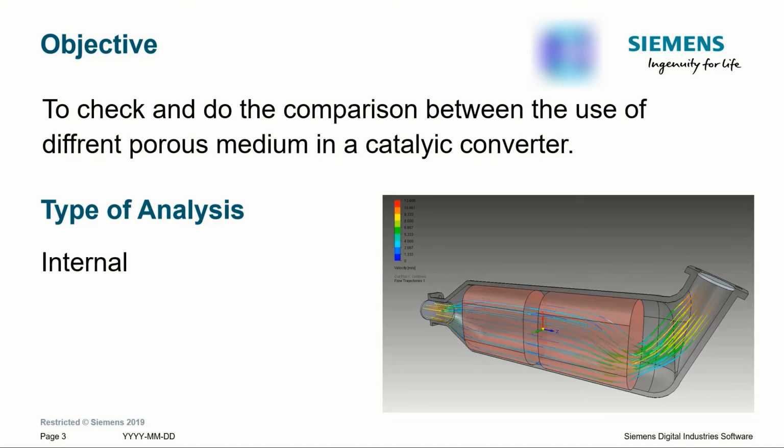where we have to select between two versions of a catalytic converter. In this tutorial, we will consider flow in a section of an automobile exhaust pipe whose exhaust flow is resisted by two porous bodies serving as a catalyst for transforming harmful carbon monoxide into carbon dioxide. When designing an automobile catalytic converter, the engineer faces a compromise between minimizing the catalyst resistance to the exhaust flow while maximizing the catalyst internal surface area and the duration that the exhaust gas is in contact with the surface area. Therefore, a more uniform distribution of the exhaust mass flow rate over the catalyst cross section favors its serviceability.